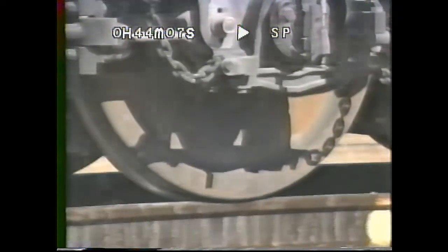Since I've been running this engine for as long as I have, I have a lot more confidence with this engine than I do with the DC unit because of all the capabilities that it has over a DC unit. One of the features that you're going to find that's really nice is the dynamic brake feature. You'll keep full dynamic brake feature down to half a mile an hour, which, as you know, in the past you didn't have with DC units. Plus, even at half a mile an hour, your dynamic brakes are just going to fade off slowly.